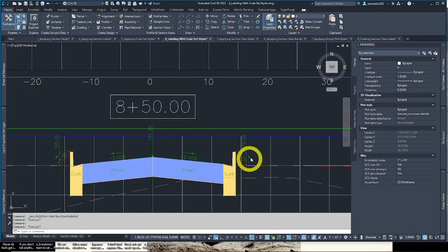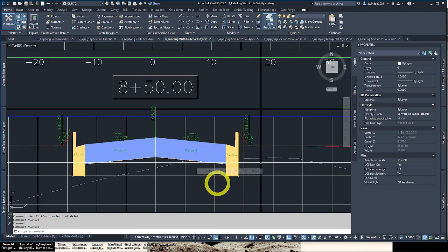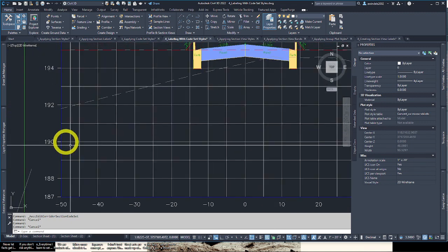Now that we've studied the display and annotations of different sections, albeit the corridor sections which have more involved inside of them, and the regular sections and surfaces, there are many similarities still between section views and profile views. Both have capability to be displayed on a grid. Both can apply vertical exaggeration to the y-axis.